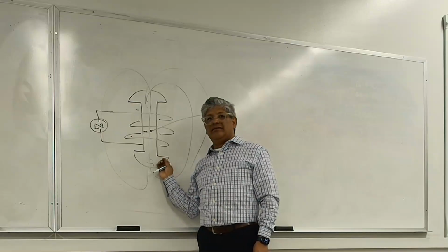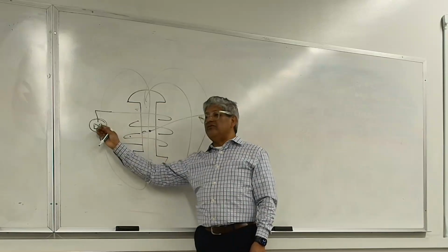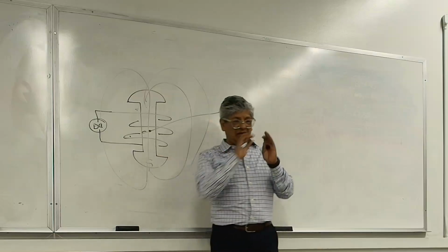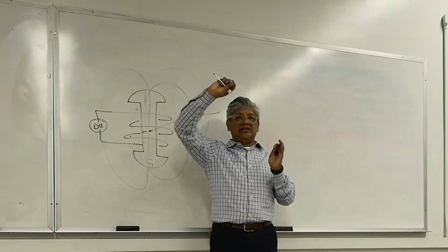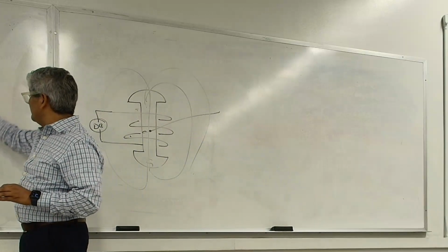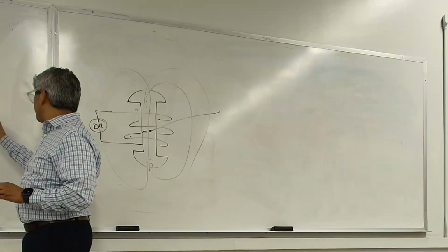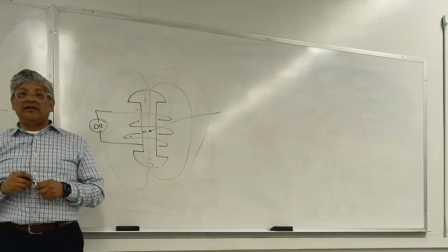That's what determines the amount of vars you're getting in and out. And you can do it very precisely. You can say, I want the vars to increase linearly, they can go up like this as a line. On the capacitor, there's steps because you're turning capacitors on as steps, right?